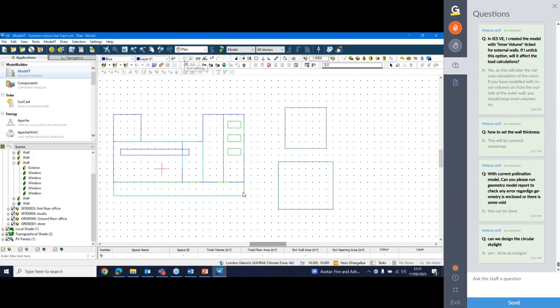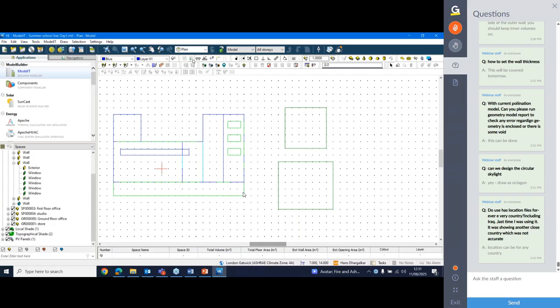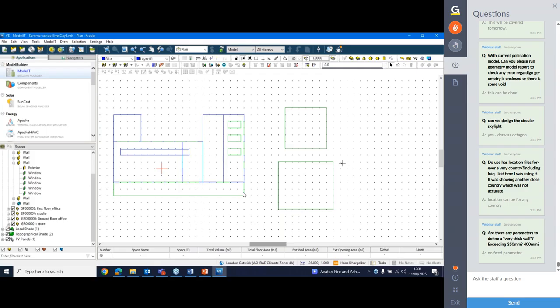And another tip, before I forget, is there's your grid settings. Very close to it is another button called grid alignment, which can actually move the origin. But I would advise you not to use that button because you can get into a bit of a twist. So don't use the grid alignment button, but you can use that to realign the origin or to line up a corner of the room with a grid. But if you've drawn a room 3.856 meters long, there's no way that you can then align all corners automatically with the grid. You're going to have to start moving the vertices. Okay.